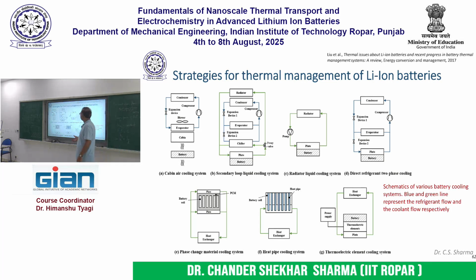For example, cabin air can be circulated through the battery pack. You can have your air conditioning system, part of which can be used for phase change cooling, where the refrigerant is circulated through the pack. You can also have a combination of heat pipes in conjunction with single phase cooling, where heat pipes, if you have the battery pack, so from within the pack, the job of the heat pipe is to transfer the heat out, from where it is then carried away by the coolant, right?